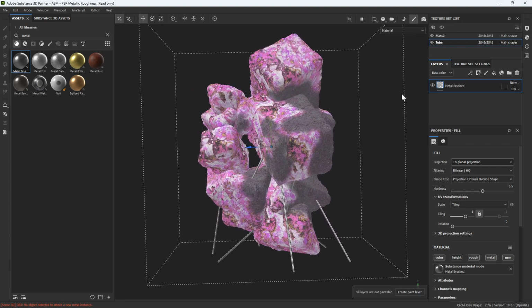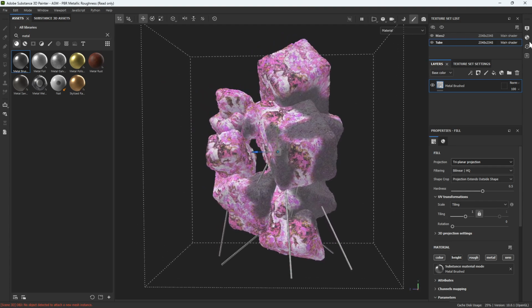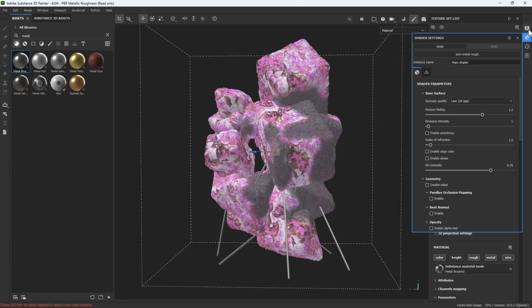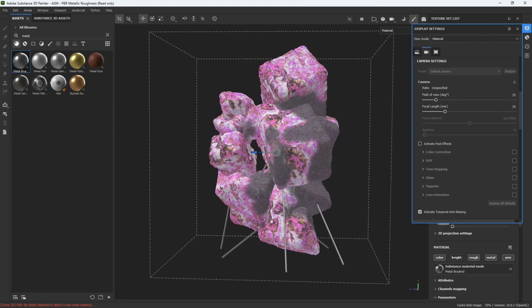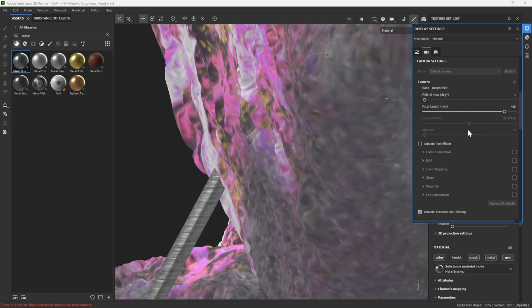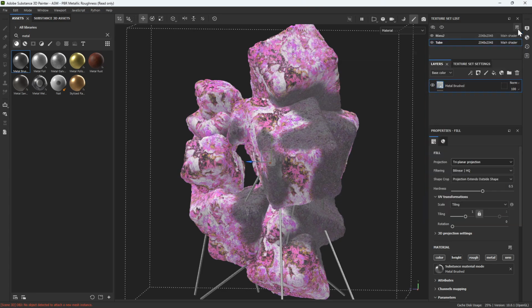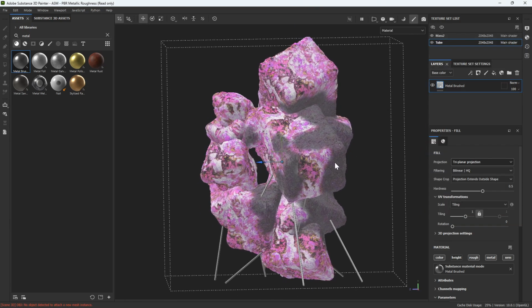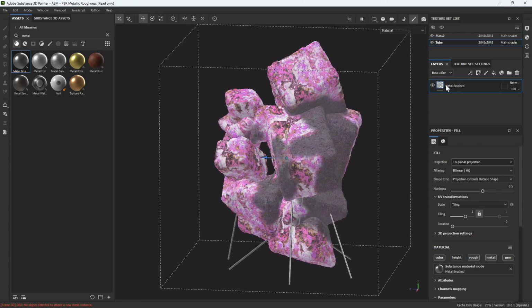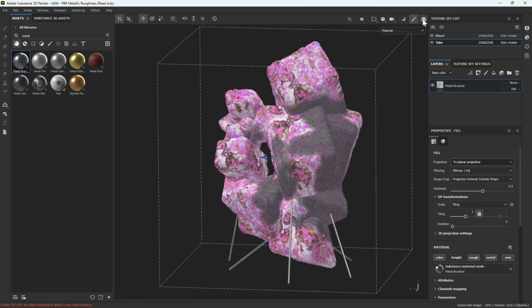Then we can start to think about a view that looks good. Let's change our camera. Our camera is more of a 35 millimeter lens, which is great. But if I want it to be more flat, like an oblique view, I could set this to a higher value. It zooms in, then I hit F, and that focuses on the object. And now I have a flatter view, and let's go to our rendering settings here.